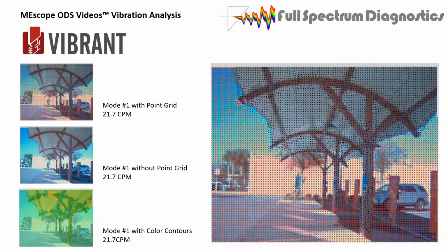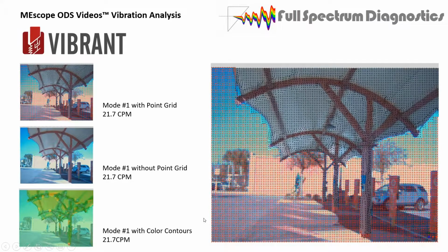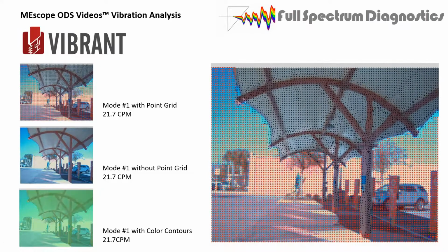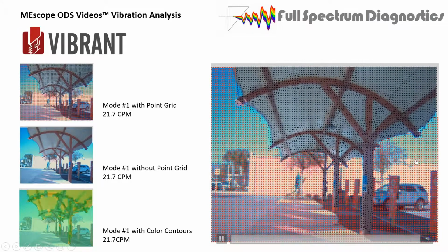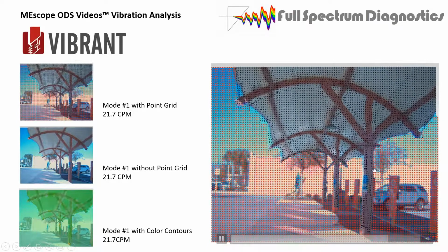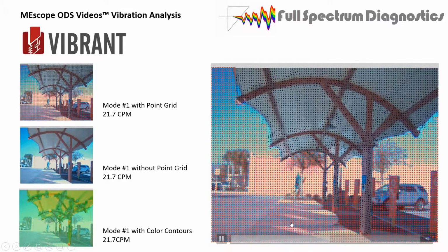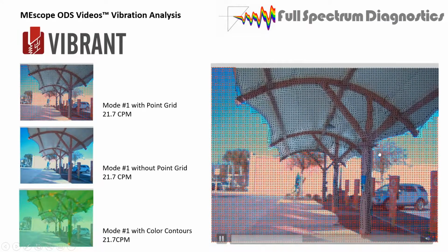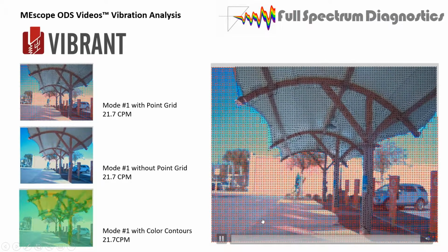This is a set of data that I took at roughly the same angle that I showed you. I left all the points on. The black points, all the beams and the canvas and everything in here, are the stuff I wanted to retain. I wanted to get rid of this tree and that tree and all this background, and there's a street where cars are going by and so forth. These are all the red points that I selected to group select, pretty quick. It takes a couple minutes to put them all in and get it all the way you want it.